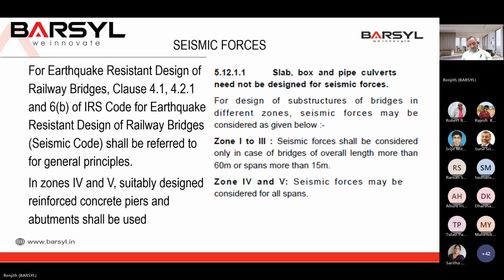Now, another lateral force is the seismic force, which also acts longitudinally. That is due to earthquake. That load also needs to be taken into consideration. But there are some exemptions. Slab bridges, box and pipe culverts need not be designed for seismic forces.